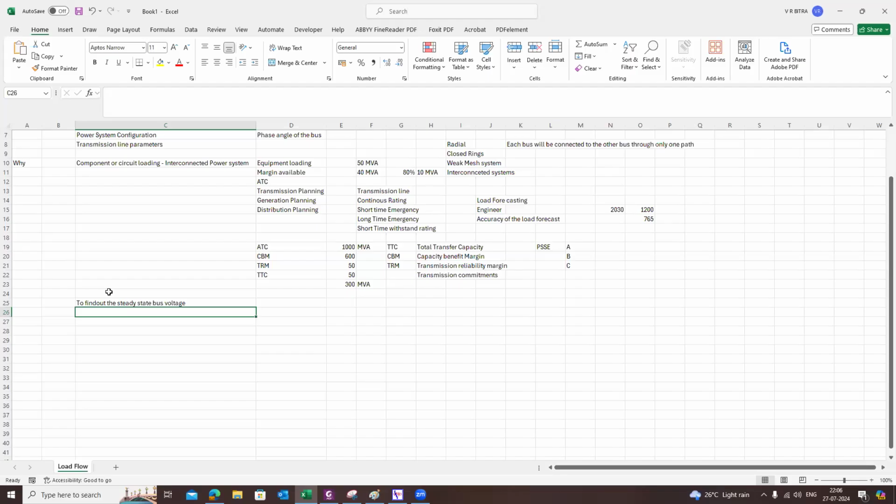And you can use the forward reverse algorithm, which is a simple Excel calculation. Add the current from one side of the network and find out the voltage drop from the other side. Like that, that's simple.